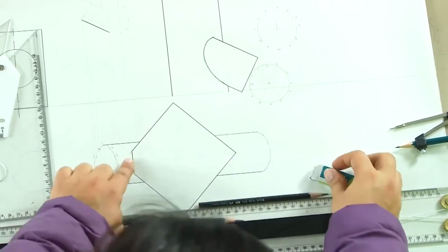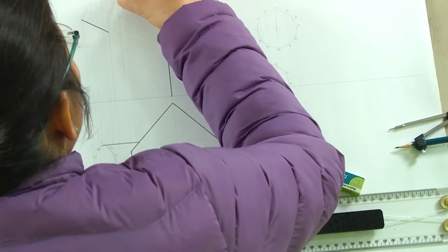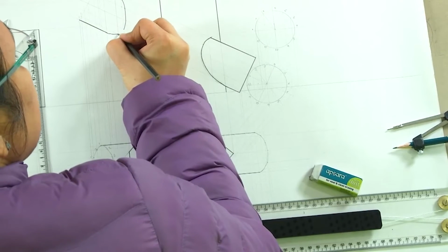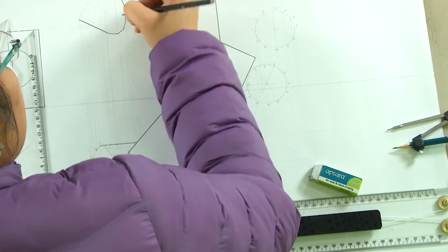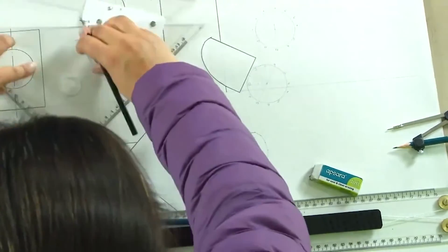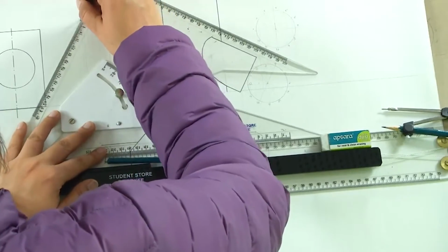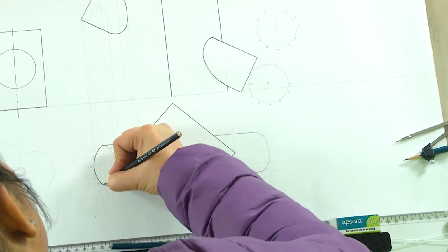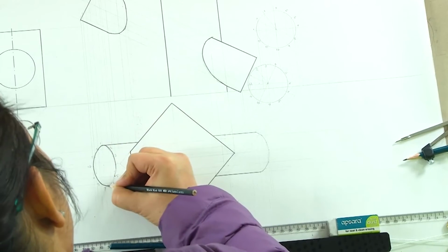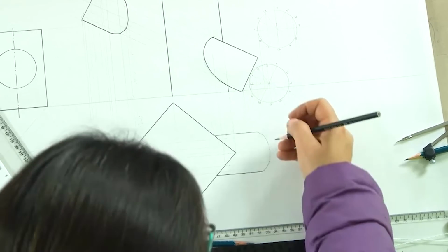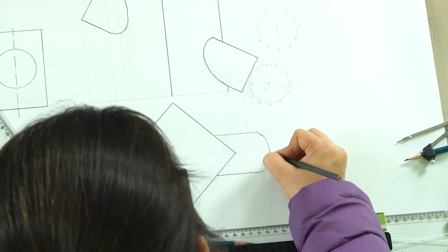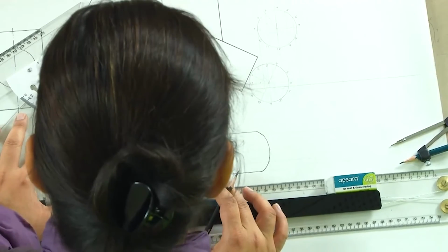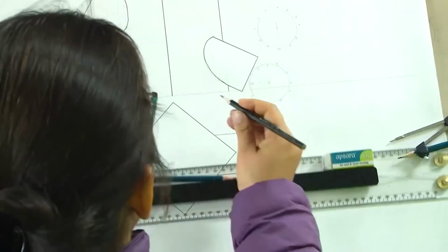So, we will have one corner of the prism cutting and cylinder entering. And you join these points, you get this curvilinear surface here. This is the ellipse at the end of the cylinder, which we will get, and this side we will only see half of the curvilinear surface of the cylinder. So, if I see this, this is where the prism is going to come.